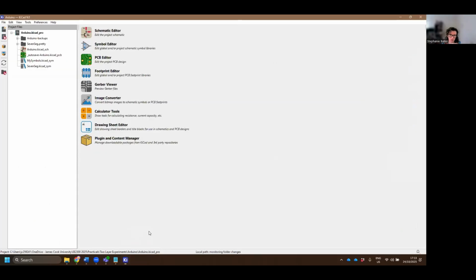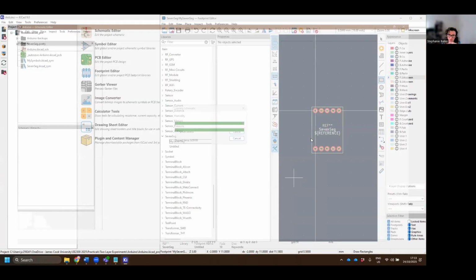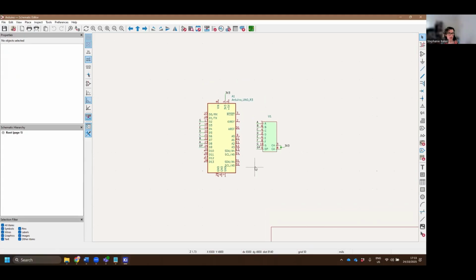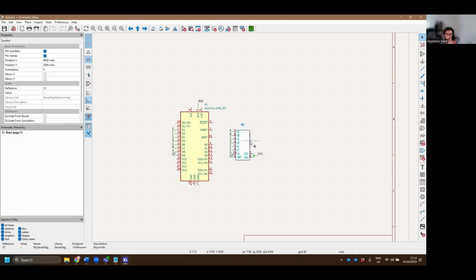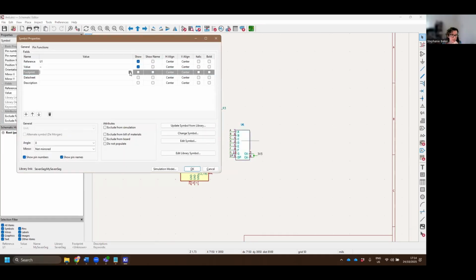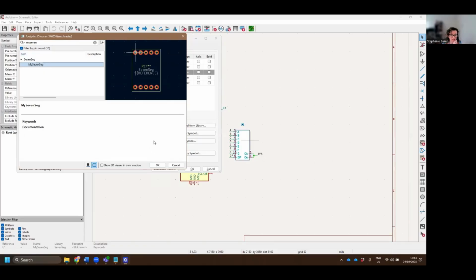Now we can go back to our schematic editor, which I'll need to open up again. Yep, it failed because, again, it crashed. So now we can save that. That looks like it did actually autosave everything correctly though, so that's all good to go. And I'm going to assign that footprint. So edit it like normal, go to the footprint library like normal, and now you're just looking for my 7seg in that 7seg library. And you can even have a look at it in 3D view, but it's not really going to show you much because it's just blank currently.